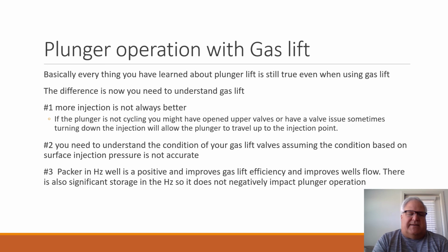Ultimately, my suggestion would be that we run tubing to 70. You land a packer around 65. You set an orifice for your gas injection just below your profile nipple, which should be in that 45 to 55 degrees. And then you put your conventional gas lift mandrels to surface as you would normally. Now, you're going to have the best overall results.